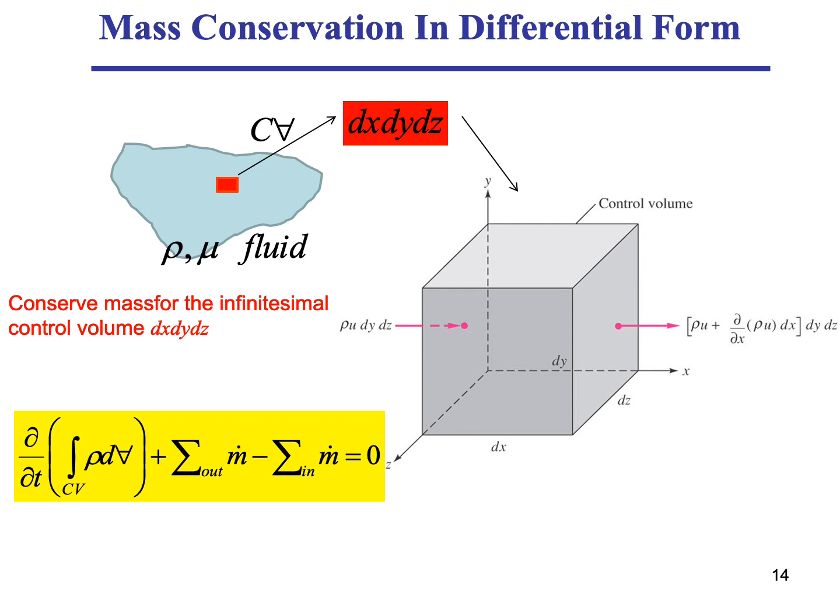Very good. The other thing you want to pay attention to is that this is a cube and it has 6 neighbors that are attached to it. It's not sitting on its own. You want to imagine that this, in its context, where it is, this is the imaginary box, the dx, dy, dz, sitting among those 6 neighbors, and mass flows coming from one neighbor to our control volume and leaving to another neighbor. It could actually come from this side and leave to the other side, and so on.